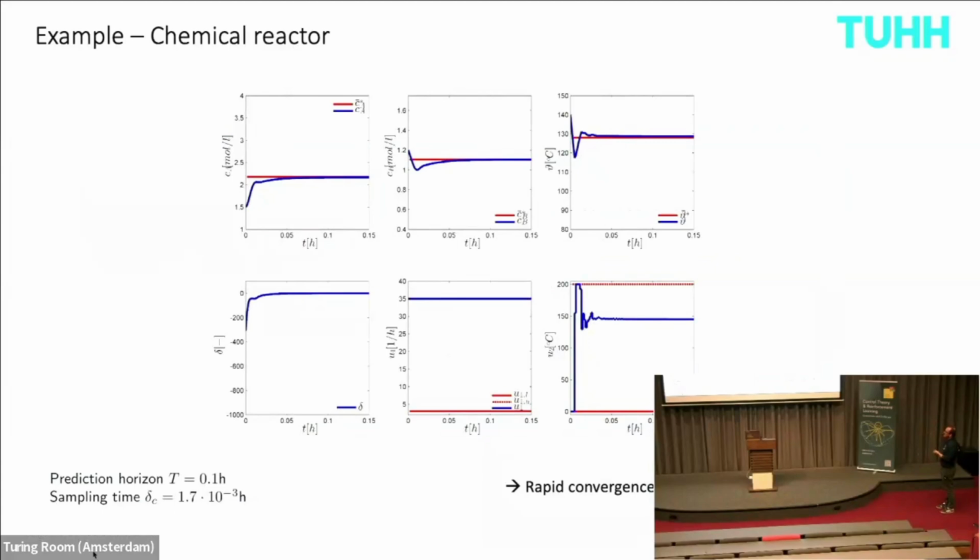In closed loop analysis, that's the same chemical reactor, and now you see closed loop trajectories. We see, oh yep, we move close to the turnpike. We change the initial condition. We move close to the turnpike. I add more initial conditions. We move close to the turnpike. So what happens if I can certify this dissipativity, my MPC strategy will automatically extract the best steady state.